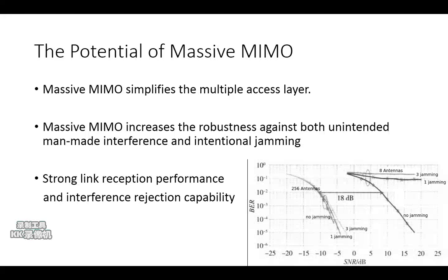substantially the same channel gain. Each terminal can be given the whole bandwidth, which renders most of the physical layer control signaling redundant.